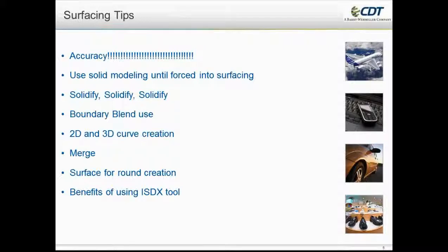Also, with more surfacing, curve, merging and solidify work, when you get a regeneration failure towards the top of your model tree, anybody that's ever noticed this knows you get a domino effect of failures that just rolls on you. You'll spend a good part of the time fixing failures, especially when you have a lot of curves and boundary blends. If you were to create some solids, sometimes you get out of those situations. So this is more of a talking point, but if you get into surfacing situations, use solids as much as possible until you are forced into surfacing.